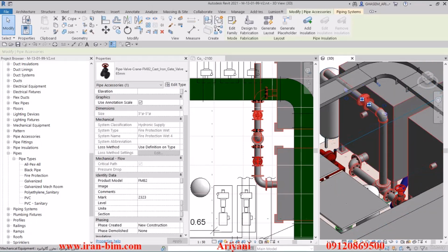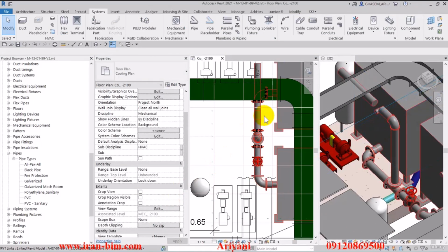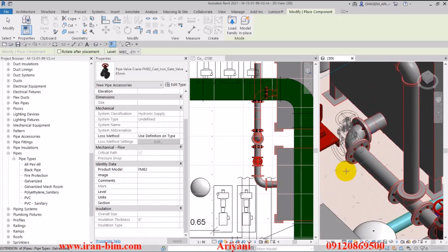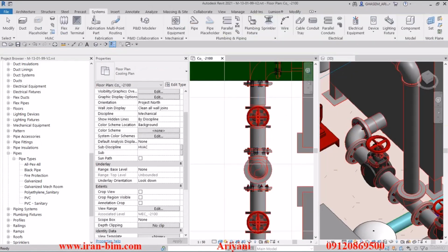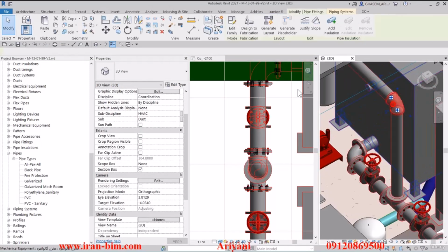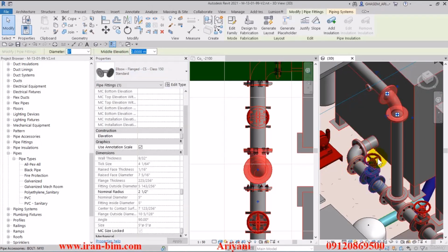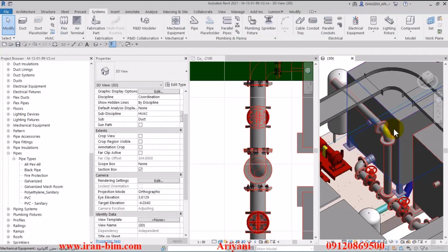And the piece that's up here we can select because it's been wrongly placed here and we need to delete it. All right, so delete this, and the reasoning for this was the difference between the surface levels and their heights. So I'll select this and using create similar, I'll put one over here, and then I'll fix this part up here using trim. And remember, we need the flanges for parts such as the elbows that we have here. So we use this elbow instead, and then we use the flanges. So basically we have to use flanges wherever we have elbows.